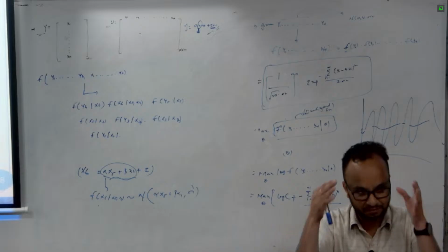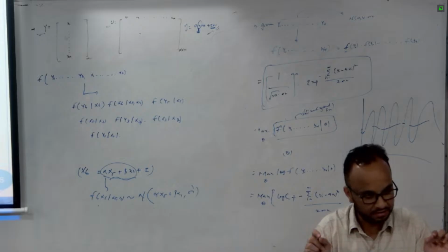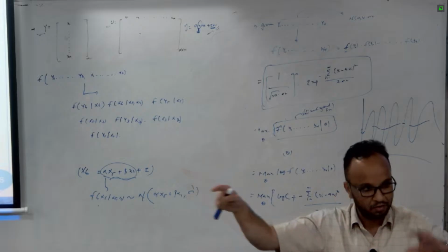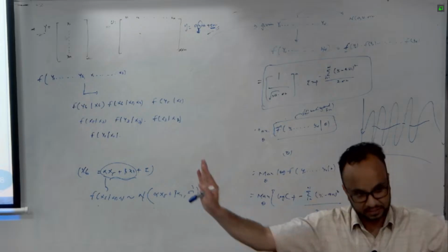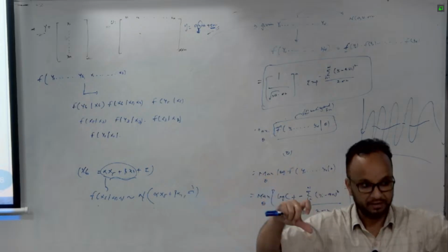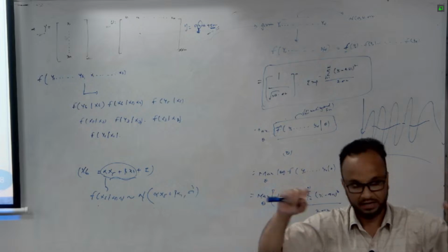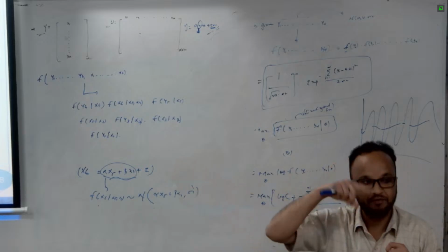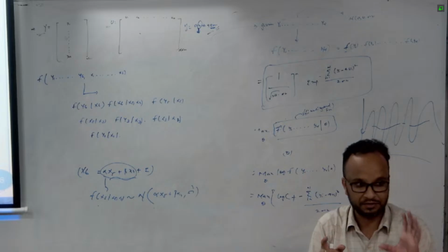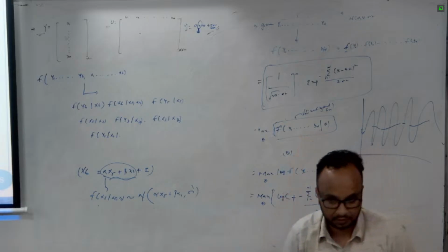So one way is to do downsampling: only select the measured data, don't select the NaN data, and remove that entire row. If you have 10 variables and there are NaNs for a longer time, just remove the entire data sets. That is called downsampling. We sample only when the measured output variables are good. The other way is to use the EM algorithm and try to estimate those hidden variables. I don't want to delete the data because data is crucial and has good information. I want to estimate it without deleting the data point.